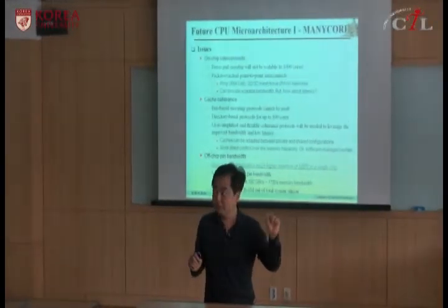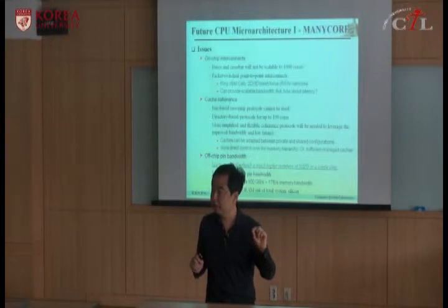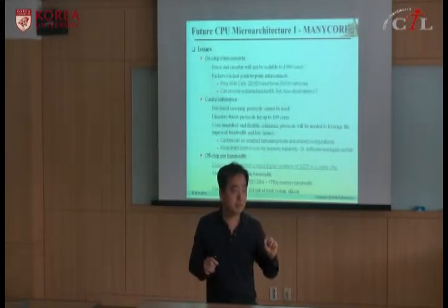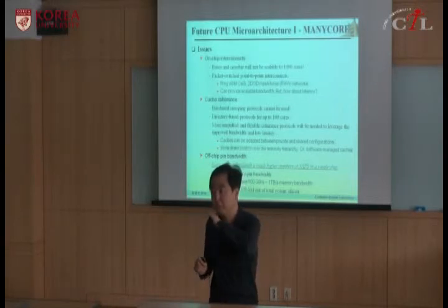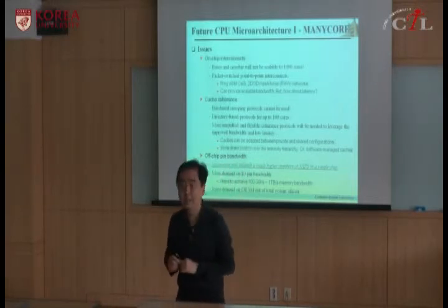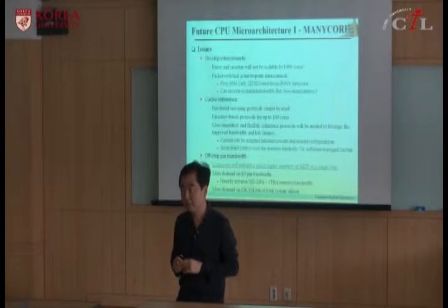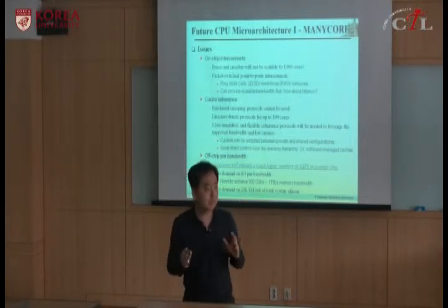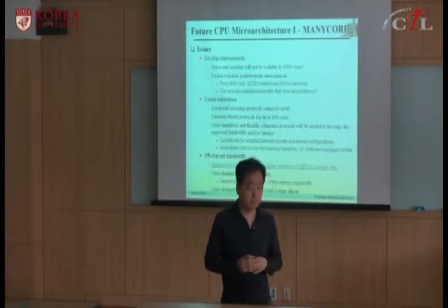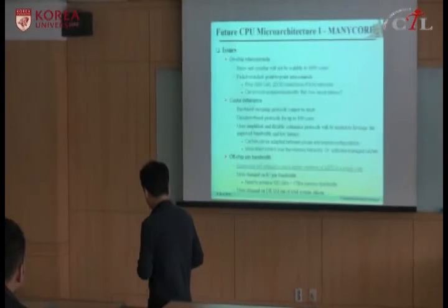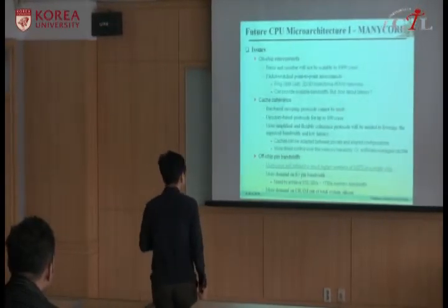Each bit tells whether that processor shares this cache block or not. So if somebody writes to that block, then you have to invalidate all the other 99 cache blocks in other processor cores, which, as you imagine, is complex. It takes time. It will slow down. And there are other versions of this directory-based cache coherence protocol, but it's only scalable up to about 100 cores.